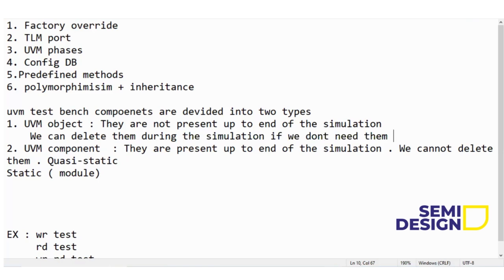See, once we are in driver and monitor, they require time. Driver and monitor work parallelly. So whenever I'm saying that my job is completed, my simulation is ended, that means driver and monitor all the work is ended. At that time, we will give $finish and we will come out of the loop. So you come out of the simulation. Once in the scoreboard, we do the checking part that doesn't consume time at all. The time-consuming part is driver and monitor.